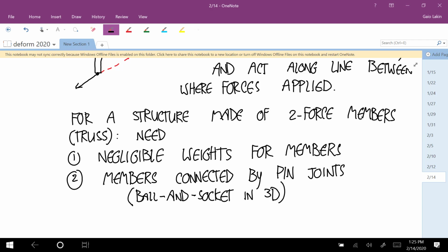And it's the same thing with the joints. If you look at a bridge and the truss that's used to support a bridge, it's never ball and socket joints that connect them. Like I said, it's these big bolted gusset plates. So those things are rigidly, really they're fixed joints. You know, they're not ball and socket joints or pin joints. But the calculations that you do using a ball and socket joint or a pin joint give you pretty close results to what you would get with the fixed joint. So you can make that simplification.